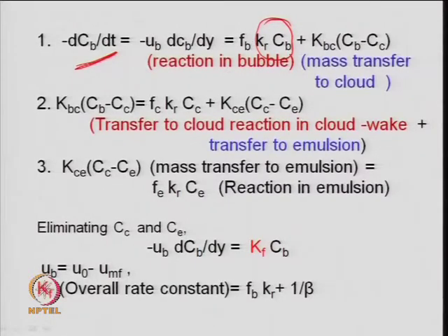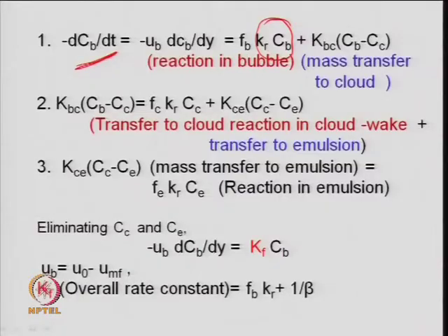So, that is why FB, because we are writing per unit mass of the catalyst there, and FB is the volume fraction of the solid in the bubble phase, although it is a low number, 0.01 or 0.001 as I said, right. So, times the chemical reaction rate constant times the concentration. So, minus rA is equal to k C_A, something like that, right. So, we are assuming a first order.